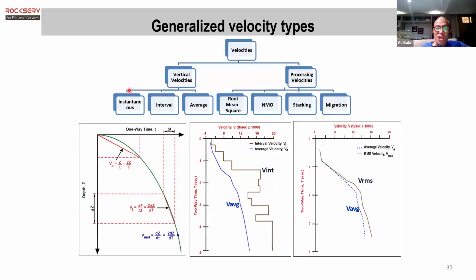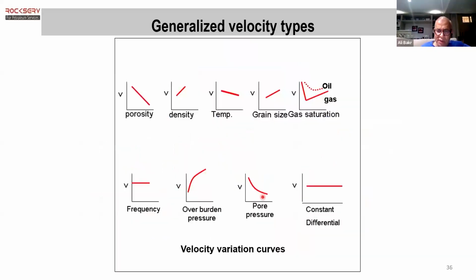And actually, we sometimes call it vertical, while we know it's not like what we have on the surface seismic ones. I put in front of you how those velocities react with time, which is not our case here. Take into consideration that velocity by depth has an assumption, the fifth assumption, that the velocity is increasing with depth. We assume this. Practically, in reality, no.